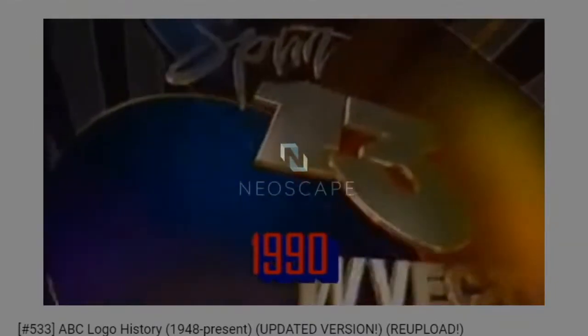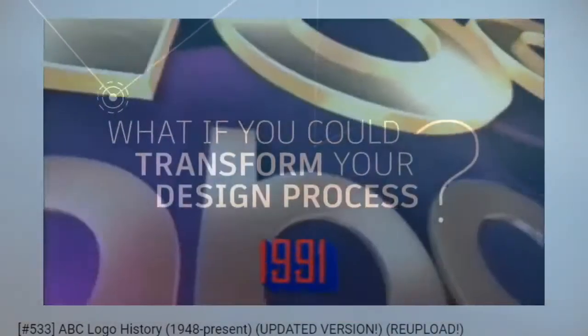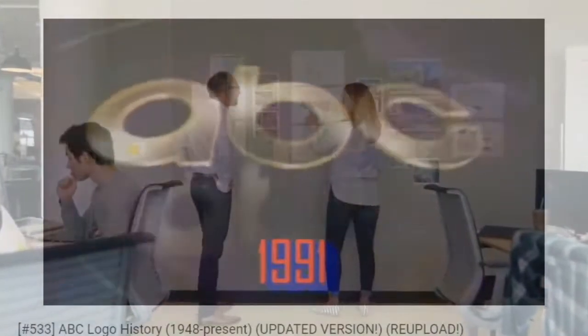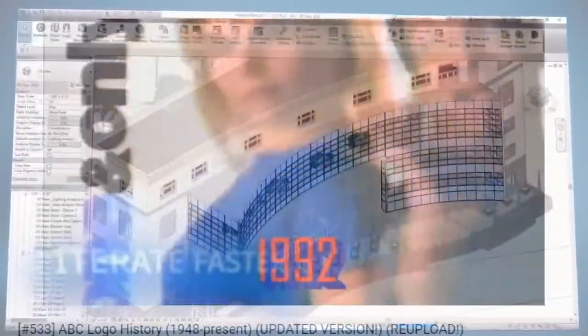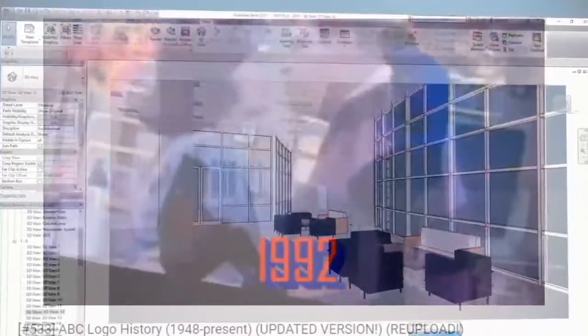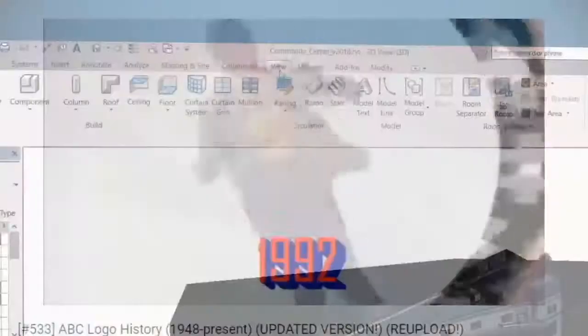Obviously the whole floor was one floor. We could put any variety of textures we want on it, and it'll schedule. So if we want to do a really quick material schedule, see if we can get it to give us what we want, do a quick material takeoff. And if I could do floors, let's see what it gives us. Let's see what parameters, what fields we could pull. Material area, material as paint, and let's just leave those two.